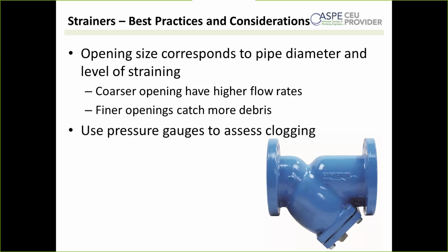Now, the pressure drop does correspond to flow rate. So if you don't have a measure of flow, it can be difficult to tell exactly how clogged the strainer is, right? When you compare your pressure drop when you check it one day to pressure drop when you check it the next day, you're not necessarily comparing apples to oranges. But by monitoring frequently and recording those pressure drops, you should be able to get a trend to tell you when it's getting ready to service.